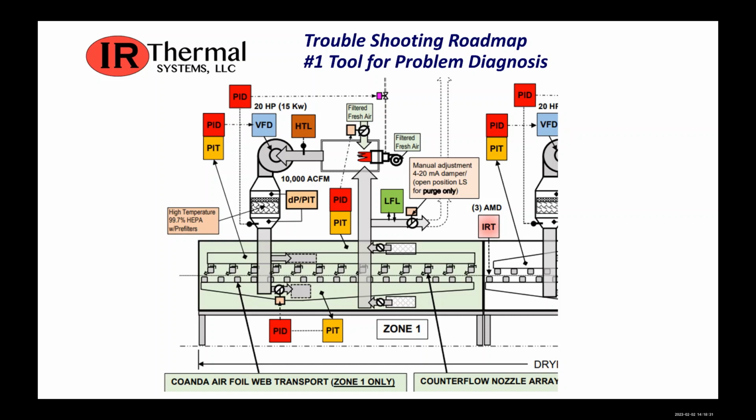So I would trace the airstream upstream of it, and I'd say, all right, the next thing on that leg is my exhaust. And I would verify the set point and the physical position of this exhaust damper. If this exhaust damper is all the way open and my exhaust fan is running at capacity, then this isn't yet the problem. It's trying to get more air and it's not getting it.